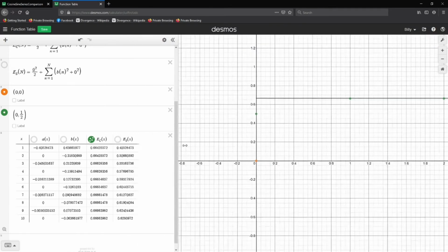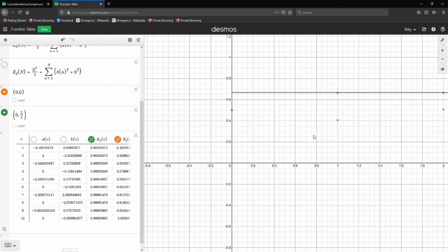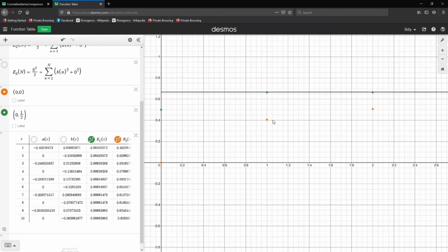On the other hand, if we look at the sine series, it's here in these orange dots. The sine series terms only start at the first harmonic, with a B1. And even if you just take one harmonic, it's not even very close to the actual energy. B1 squared is right here, which is a little bit more than half of the actual total energy contained in the signal.